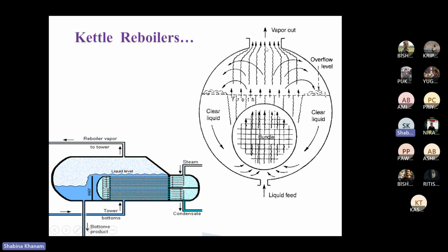And here, when vapor is exiting, this space is called the dome segment. Okay, this particular section is called the dome segment. And the vapor which is exiting from here takes liquid droplets with it, basically entraining the liquid droplets. And this space is provided to have vapor separation, so complete vapor is exiting out. Okay, and liquid will remain there.